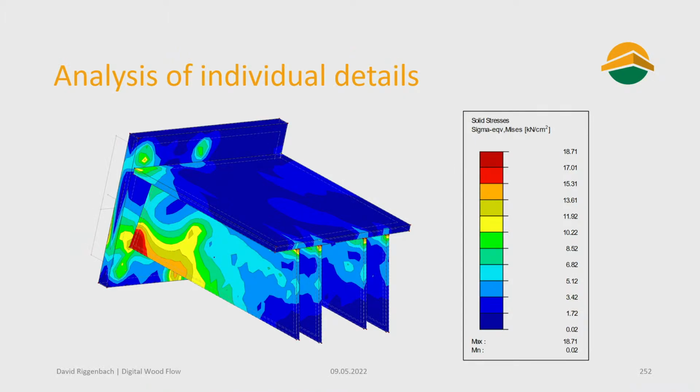Then the steel parts are exported to the program for structural analysis, where they can check stress in every detail. And this, again, is an iterative process. You first do a rough estimate, you model the piece, you double check the structural forces. Sometimes it works, sometimes they are overloaded, sometimes they are too big, and then you have to do another loop. Every loop needs to be calculated for 24 hours.